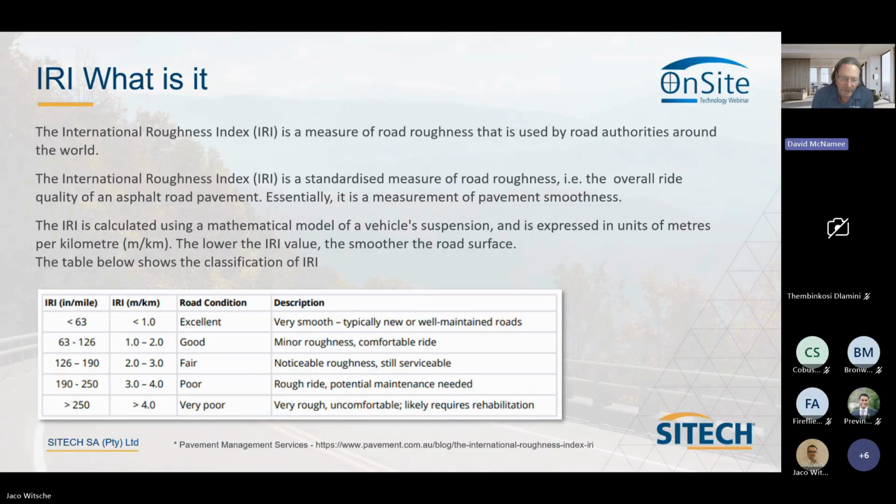So if you've built a surface and you've gone off and scanned it with mobile mapping or SX12 scanners, or if it's an asphalt paver, you can bring those paving files back into TBC. You can then run this IRI command against that as-built data.